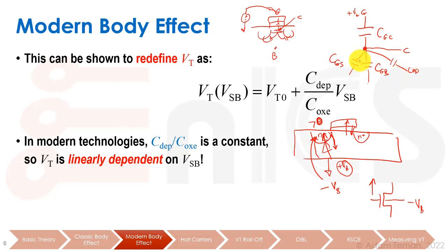These are bothering us, because when we try to pull our transistor to VT, these guys are holding it to a different voltage, and that's something we don't want. We want to have total control with our gate terminal, and these guys are really fighting us. That is actually our subthreshold slope, which we're going to discuss with leakages. We want to fight that. We want to combat it. We want to take it down.